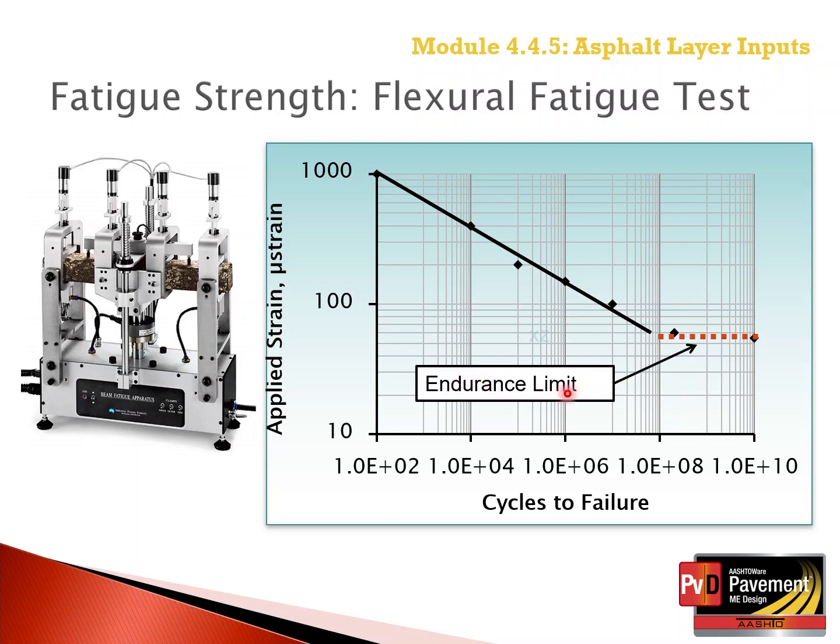So again, the endurance limit is defined as the strain level at which no damage accumulation occurs for cracking. So the bending beam will perform basically forever without cracking.